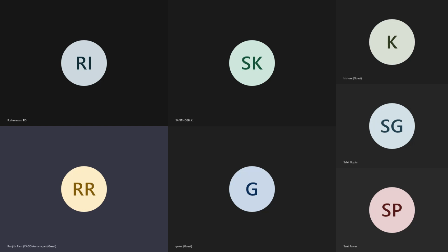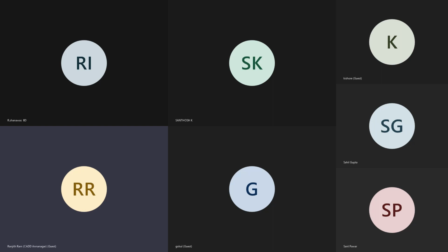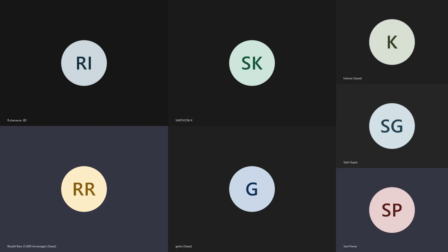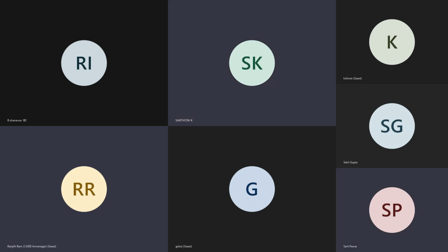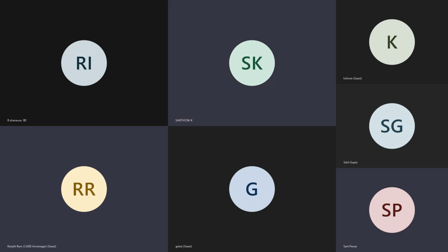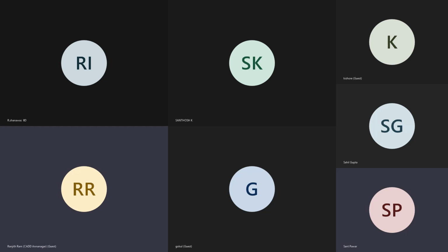Once we created that, we move on to the Fluent environment, and we have so many things to define, the general conservation equations like mass and diffusion factors, and accordingly we have to define that first. Once we define that, we need to assign the boundary conditions like inlet condition and outlet condition. Once we give that, we move on to the solution and look for convergence, whether the problem is converged or not, and we move on to CFD-Post and view the results. So that's the overall basics, but we haven't yet got into the core of it. So why are we choosing laminar flow other than that?